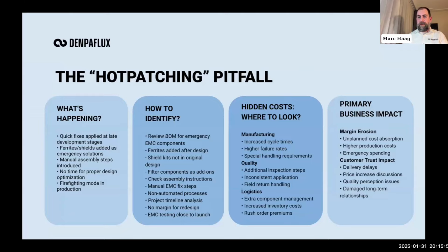When it comes to an EMC foil, it needs to be a proper and smooth process, and you have to ensure that it really sticks to the product correctly. Or ferrite beads: if you have to wrap them around the wiring harness, it's a little bit tricky. Most companies, when they have small batches, either purchase the part with the ferrite bead directly from the supply base, or they do it as a manual process.